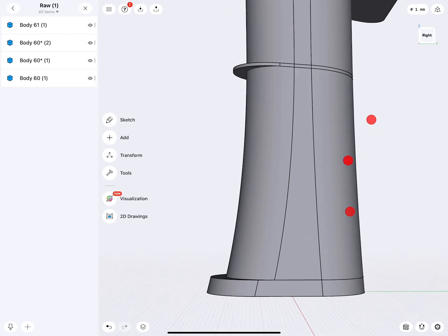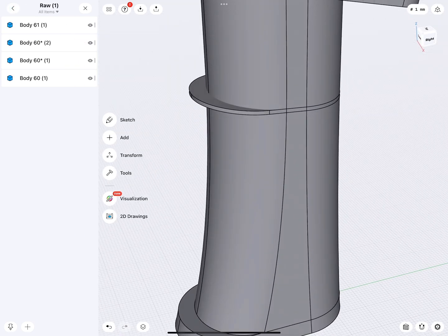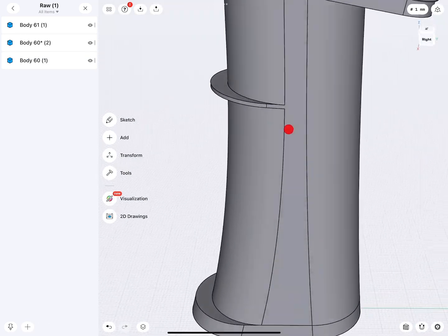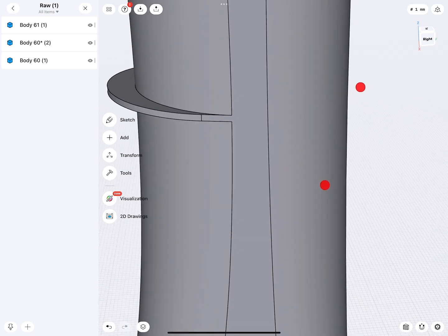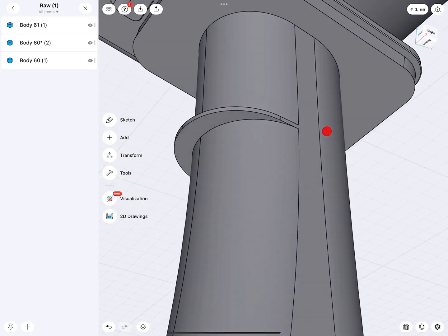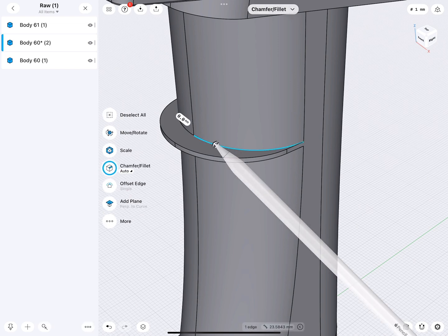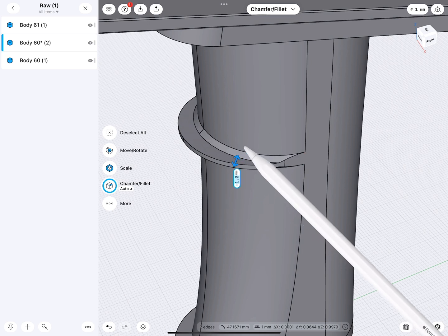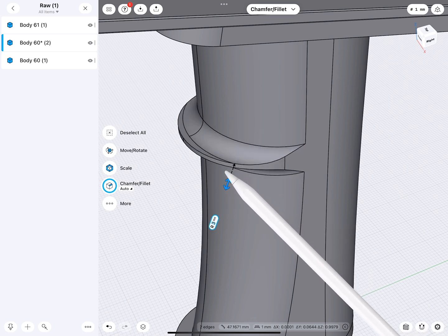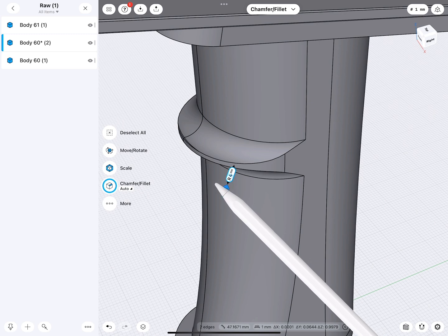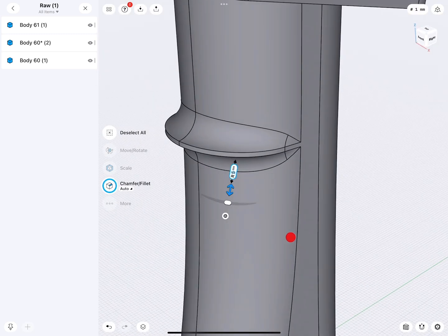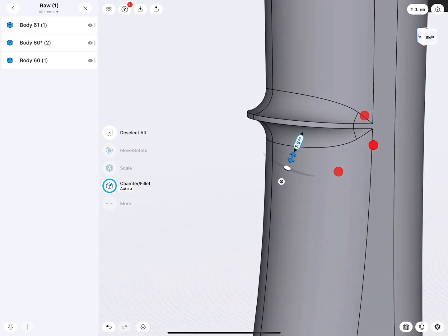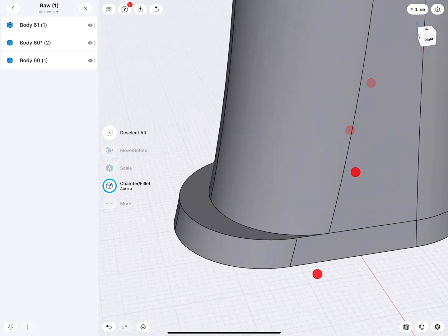Hide the previous one. And now I can go ahead and test here. So you and you join. So when I join you, what will be the result? Oh, that actually looks pretty good. You see in the back, this is all gone. I only have this edge here. Now I can select this edge and do a nice fillet and study how this looks. This is beautiful. You see now how here at the ends, the fillet actually switched and is coming down. This is really nice. Very good.